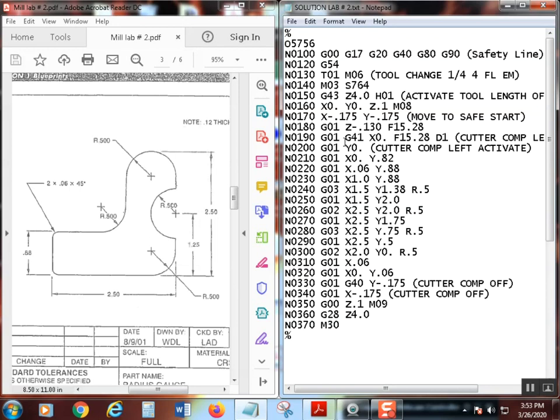All right. Once I have gone ahead and moved to X0, so I was down here, I've moved over here. Then I'm going to go ahead and move it to Y0. So instead of actually making a move like what you would expect it to do, it'll do something like this, and it'll stop right there. So it'll be here, X minus 175, Y minus 175. Then we do those two moves over and up, but it'll actually go whoomp, and it'll stop right there. Yay. Okay. Now, we're not going to call that any point at all right now. Later on you can put the points. I find that people number points any way they want to anyhow, so it doesn't really matter.